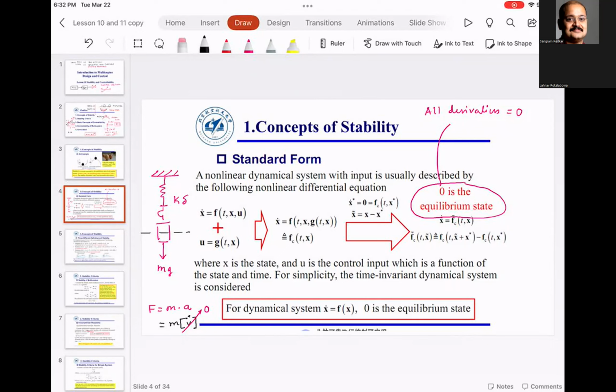Everyone understood this? That is what it is. For circular path following, you will have to implement some type of heading control, which means you need to implement a controlled yaw. That is more complicated. But I think at least level flight and straight flight, we should be able to do.